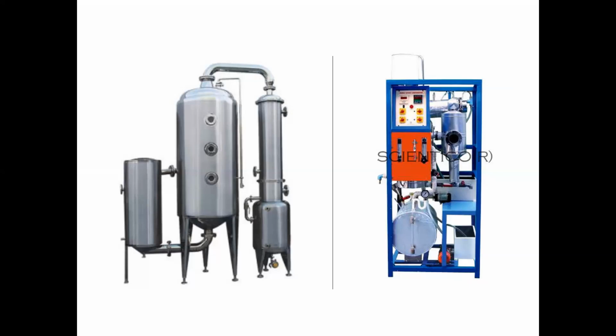So create a lower pressure at one location, and then the vapor is going to flow in this direction. This is how you drive vapor to move, not only in a single effect evaporation, but also in multiple effect or multi-stage flash systems, so that you have an increasing trend of pressure reduction going from one stage or one effect to the other.